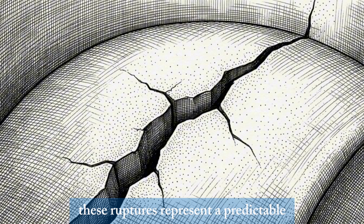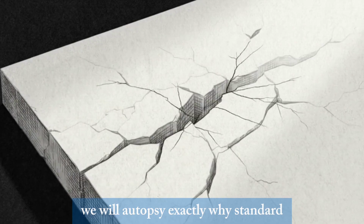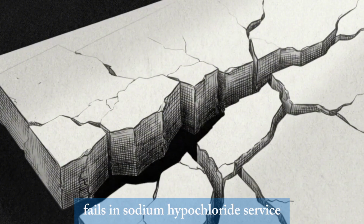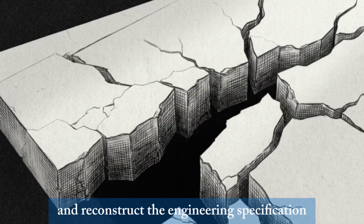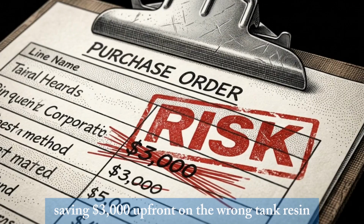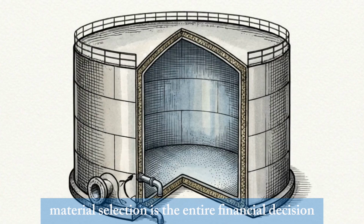These ruptures represent a predictable material science failure triggered by specifying the wrong resin for an oxidizing chemical. We will autopsy exactly why standard linear polyethylene fails in sodium hypochlorite service and reconstruct the engineering specification required to build a zero-failure system. Saving $3,000 upfront on the wrong tank resin creates a massive future risk profile. Material selection is the entire financial decision.